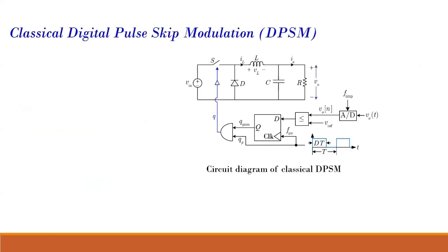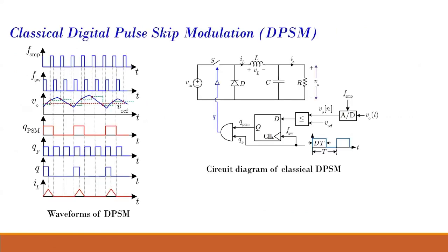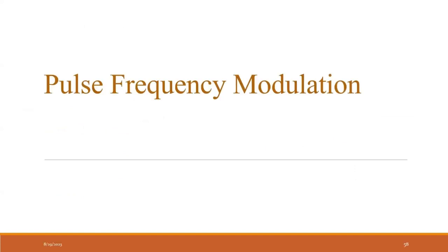Next we'll consider pulse frequency modulation. So what is pulse frequency modulation? It is also known as PFM. This is a light load technique. In light load condition, what happens is pulse width modulation runs at fixed frequency.